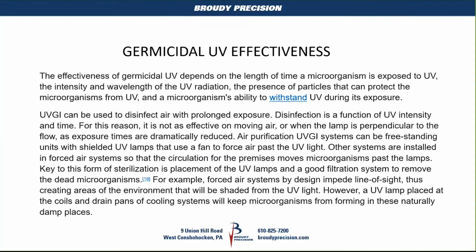A lot of how well this technology works is the length of time a microorganism is exposed to the UV, the intensity of the wavelength of the UV radiation. There are other things like the presence of particles that can protect the microorganisms from the UV, the microorganism's ability to withstand UV during its exposure, mutated type microorganisms. It can be used to disinfect the air with prolonged exposure. So disinfection is a function of the UV intensity and time, very shortly put.